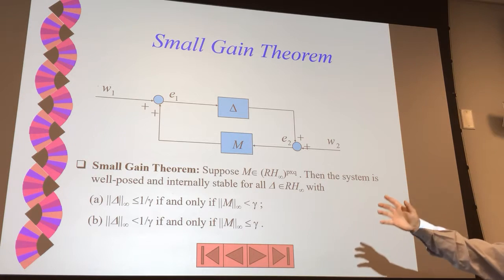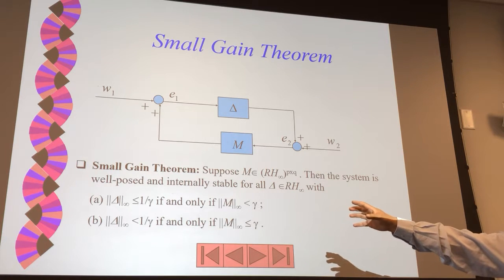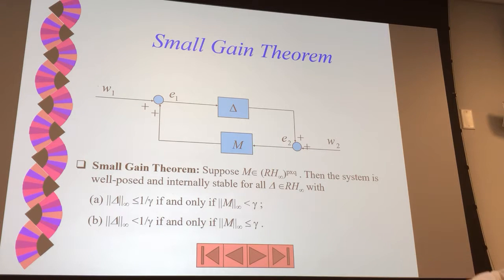So at those frequencies, it is actually positive feedback, right? So if you say my system is always negative feedback, that's actually wrong. You should say, yes, I'm using negative feedback for the signal, but at certain frequencies, some signal components are actually positive. Make sense?